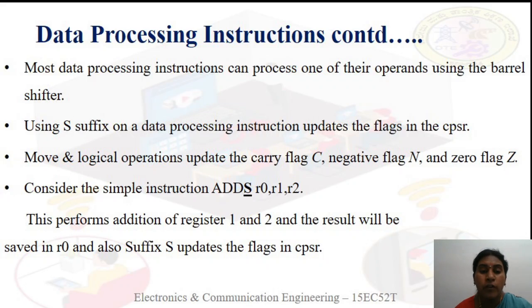So by putting the suffix, you can update the flags in the CPSR. To update the flags in the CPSR, you have to put the suffix S in the instruction. Okay.